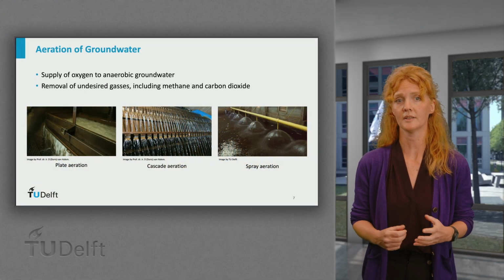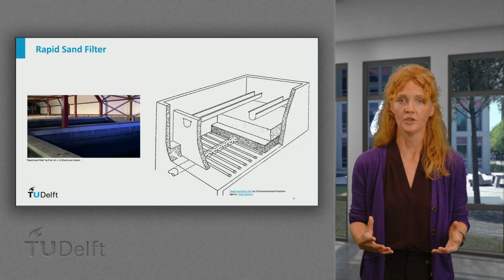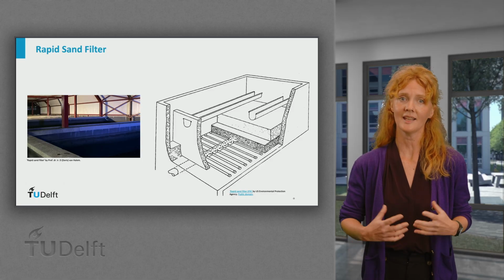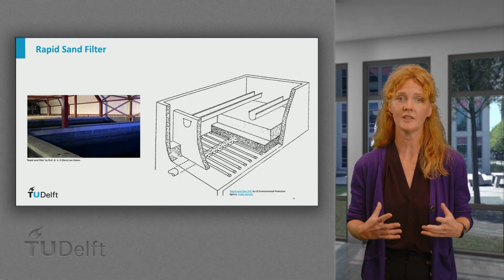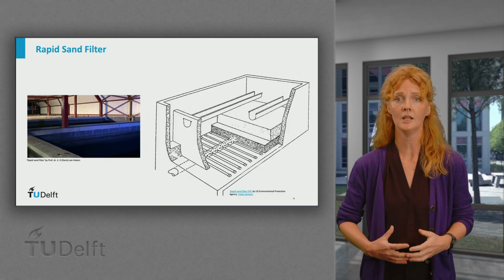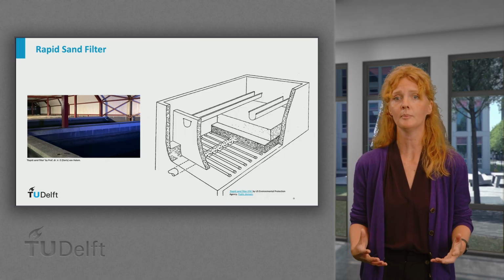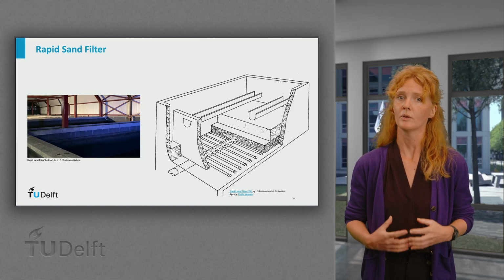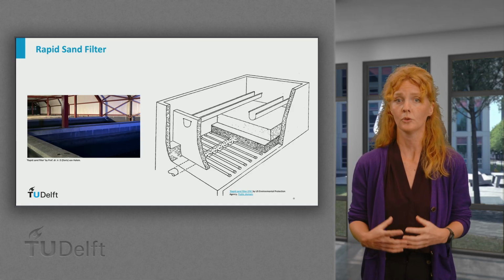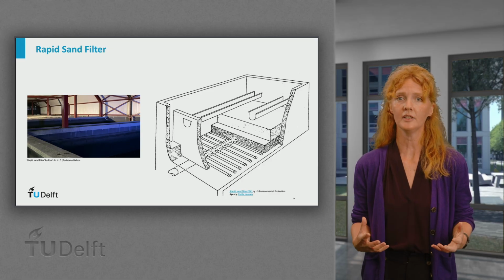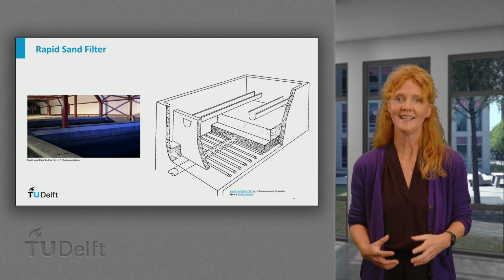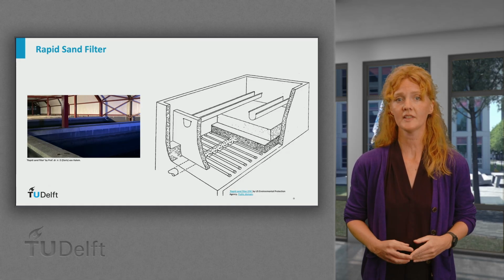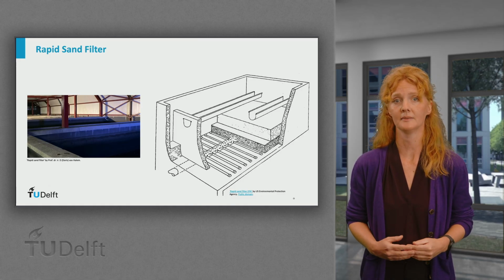After aeration, the water flows on top of the sand filter, which is a packed sandbed saturated with water. On top of the sandbed is a supernatant water level to ensure air bubbles will not enter the pores. At the bottom of the sandbed is a support structure with drainage pipes and coarse sand, coarse gravel. By gravity, the water flows through the filter bed in a downward mode, with flow being controlled by a pump or simply by the water level and a siphon.